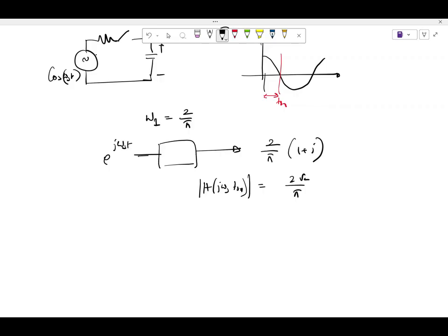We all agree with that, right? So it should be flat, which means it's almost a DC, right? Which means no high frequency component exists. Correct? Agree with that? So which means that if I put a band pass filter at the output at omega s or 2 omega s or 3 omega s, I should get near 0. Right? I should only get outputs around 0.